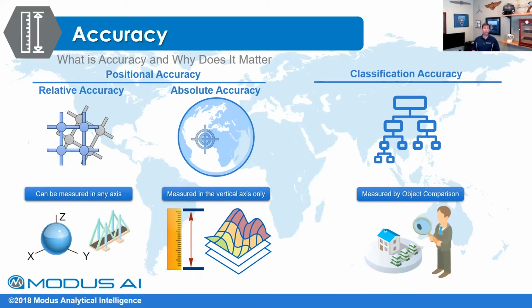Okay, absolute accuracy, on the other hand, is just that. And since I'm dealing with surveyors, I know you guys get it: when you set up your control points, how far is the deviation? How many points are you going to need? Everything's measured in root mean squared or your 95% error. So there are very strict standards, whether you're following surveying standards or FEMA standards, which we'll talk about in a minute, or USGS or even ASPRS.